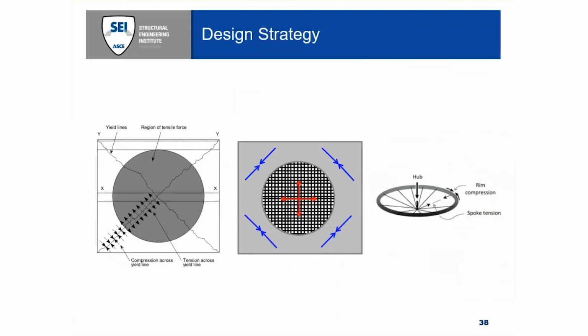So if designed properly, this enhanced case would allow for floors to become stronger and stronger as they deflect under elevated temperatures. This mechanism is referred to as compressive tensile membrane action. This would be analogous, as shown on the right side, to pushing down on the center hub of a horizontally oriented bicycle wheel, in which the system stabilizes itself as a tensile membrane with forces in the spokes that are in tension, equilibrating with compressive membrane forces along the periphery of the rim.